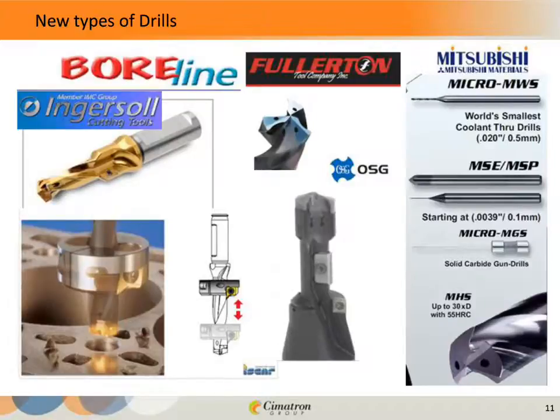And of course, with the through the spindle coolant, we don't do any pecking, which is kind of what this presentation surrounds, is the ability to just blast through steel without doing any kind of pecking.